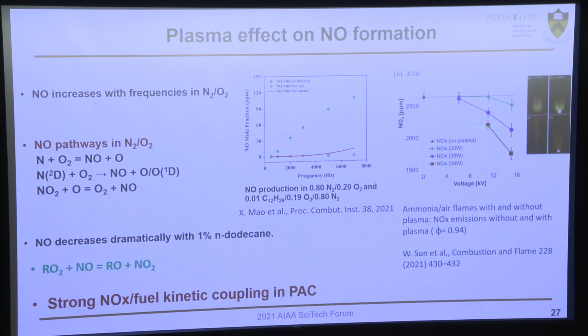Wen-Ting did a wonderful experiment to show that plasma-assisted ammonia combustion, as I said yesterday, dramatically reduced NOx. That's probably because the NH2 reaction with NO reduced the NO formation.